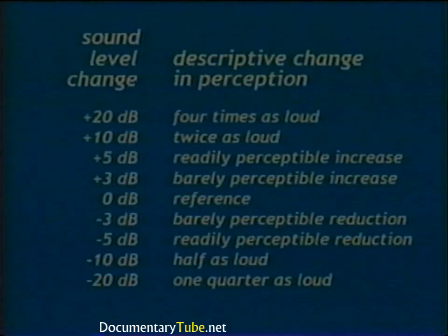We can take a look at examples of descriptive changes in perception and their corresponding sound level changes. When the sound pressure level increases or decreases, some humans in a normal living environment can detect a loudness change if the sound pressure level is altered by 3 dB or more. A change of 1 or 2 decibels will usually go unnoticed. A 5 dB change, on the other hand, can easily be detected by most people.